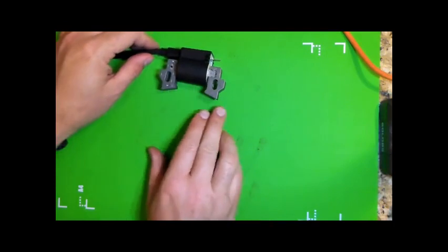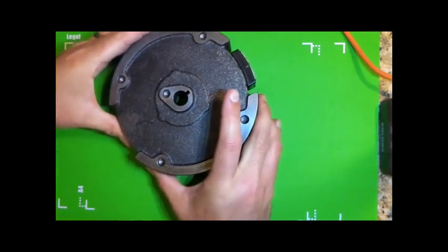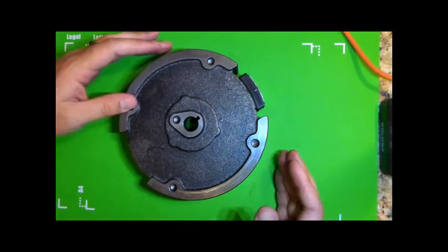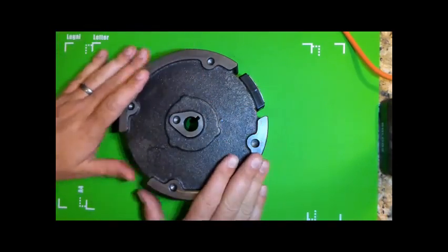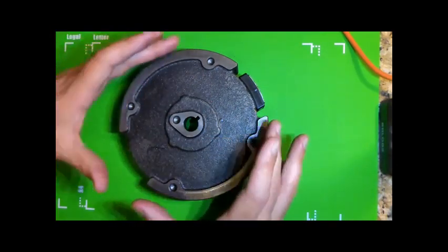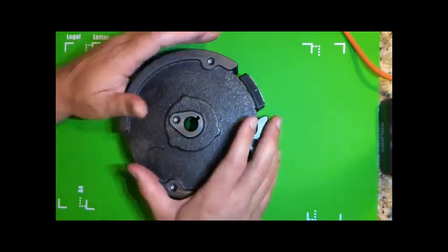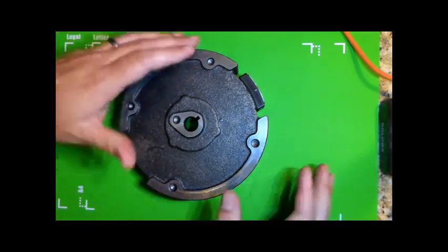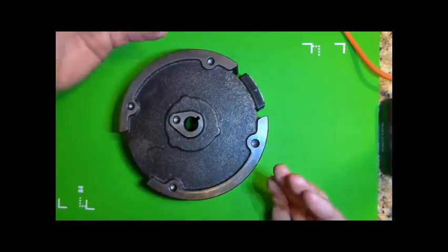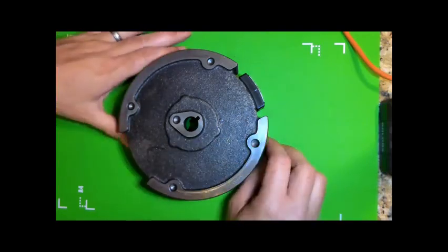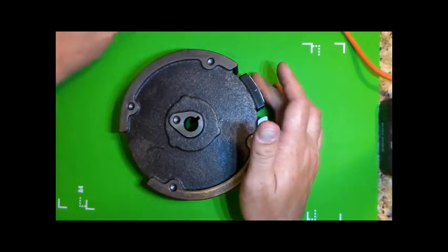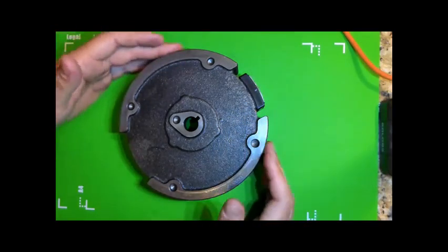And this curved area is what's going to ride right next to the flywheel, and this is the flywheel off of these engines. Other flywheels you may see in engines may have metal fins built into the face. This particular engine has a set of plastic fins that simply attaches when we put the flywheel cup on, which we'll look at in a minute. But again, to review, the fins simply keep air moving around the engines. These engines are air cooled. This is the magnet that's going to really be the central piece of the flywheel that's going to create electricity.